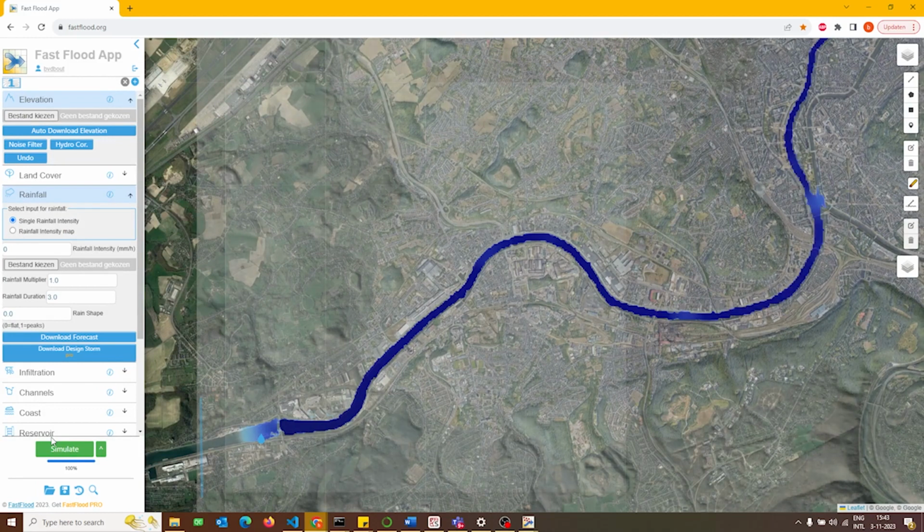And there we go, we have our results. So what we see immediately is that at the moment there's no flooding. The water is contained within the river. Now here the actual estimate of the river shape in the elevation model is quite good. The improved accuracy of the Copernicus global elevation model helps with this. This is not always the case. It's usually really good to check these kinds of things. Calibration and validation is critical when using these kinds of results.